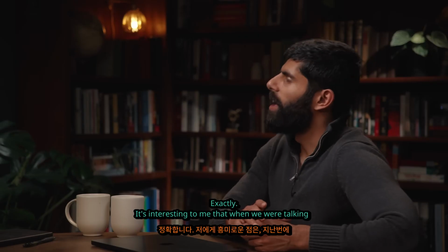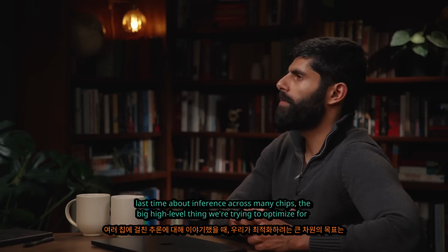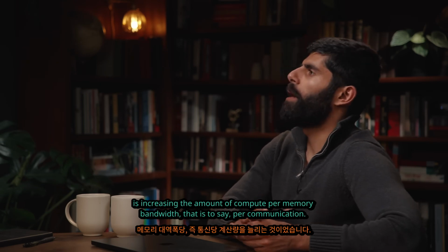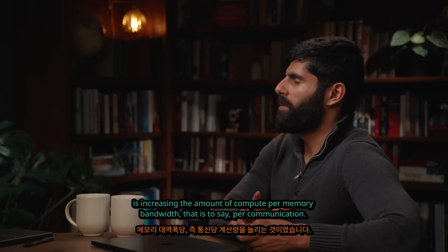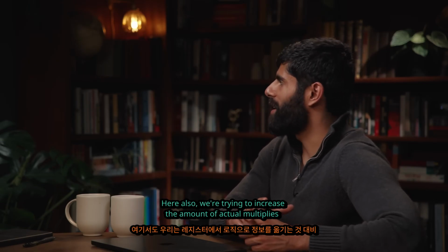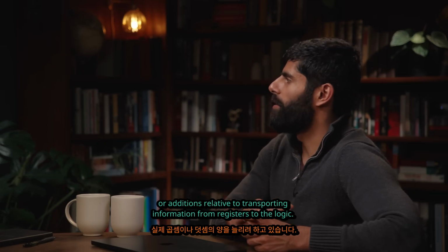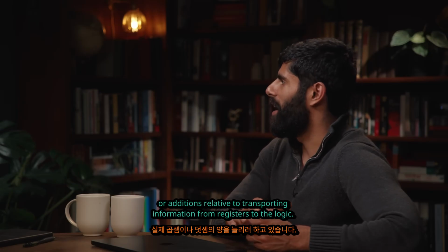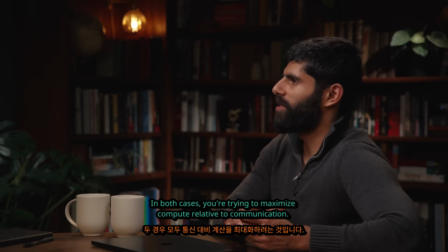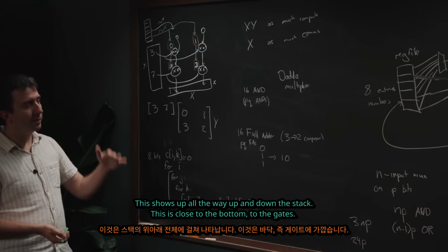Exactly. Interesting. So it's interesting to me that when we were talking last time about inference across many chips, the big high-level thing we're trying to optimize for is to increase the amount of compute per memory bandwidth, that is to say, per communication. And here also we're trying to increase the amount of actual multiplies or additions relative to transporting information from registers to logic. So in both cases, you're trying to maximize compute relative to communication. Yeah, this shows up all the way up and down the stack.